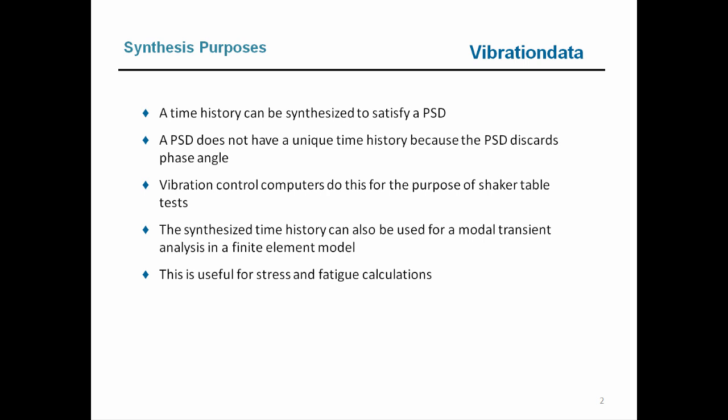And that actually allows us some flexibility for a shaker table test of a component, for example, because that allows the control computer to come up with any time history it can in terms of its own phase variation. And as long as that time history has a g² per hertz magnitude that satisfies the specification within some reasonable tolerance bands, then that time history can be used as a base input to the component or test unit, whatever it might be.